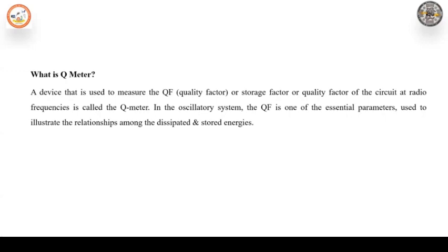A high value of Q is always desirable as it means high inductive reactance and low resistance. A low value of Q indicates that the resistance component is relatively high, and so there is a comparatively large loss of power. The effective resistance of the coil differs from its DC resistance because of eddy current and skin effects and varies in a highly complex manner with the frequency. For this reason, Q is rarely computed by determination of R and L.